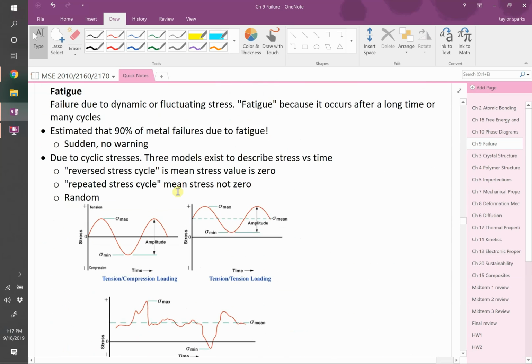All right, let's switch gears and talk about, or were there other questions I can answer? Yeah. So if it increases in energy absorbed, that means it gets more. Yeah, so if it took more energy to snap that thing, so the thing swung down but it didn't go up quite as high, that means that more energy was absorbed, which means that this was more resistant to fracture, so it had a higher fracture toughness, right? Had a higher fracture toughness because it took more energy to fracture it.